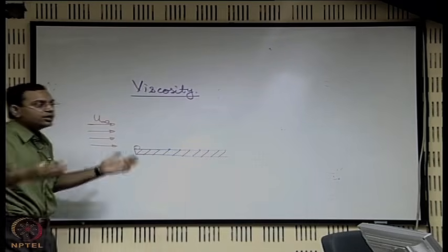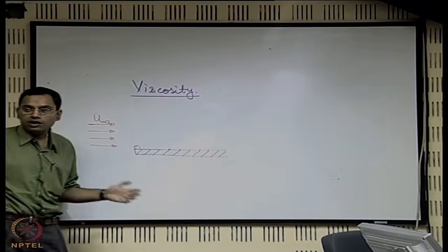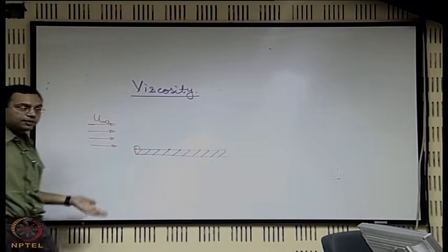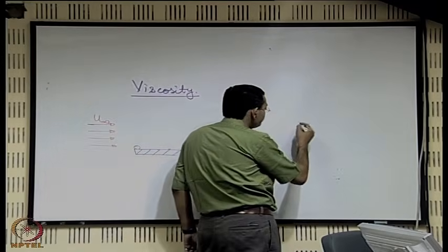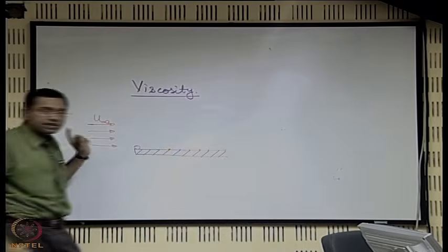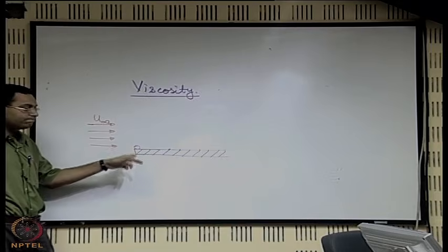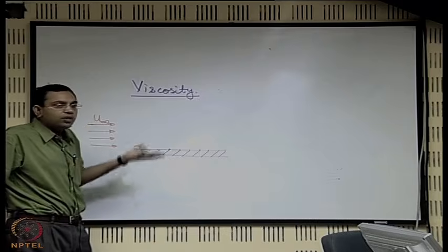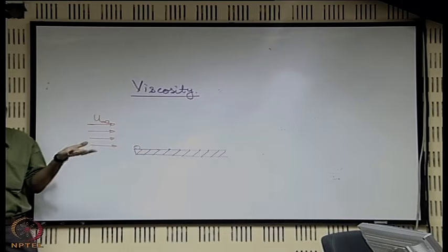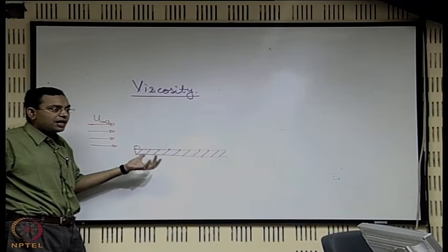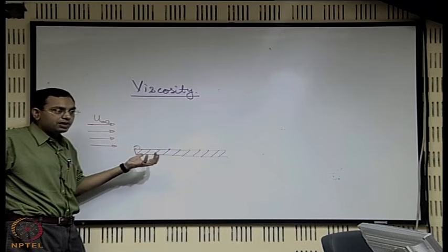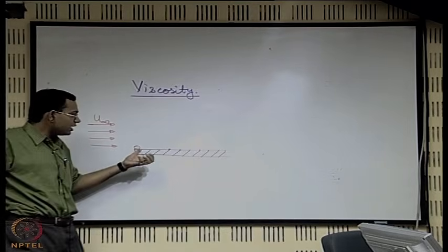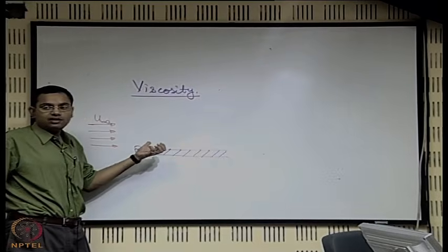Usually whenever we discuss fluids, we are either talking about gases or liquids, but sometimes it is better to discuss their physical behavior distinctly or differently. So, let us say that there is a gas molecule, as a first example, which is falling on this plate. What will happen? There will be first a tendency that the gas molecule is adsorbed on the surface. Once it is adsorbed on the surface, it will exchange some of its momentum with the surface. It will try to have it slowed down, and then again it will try to be ejected from the surface.